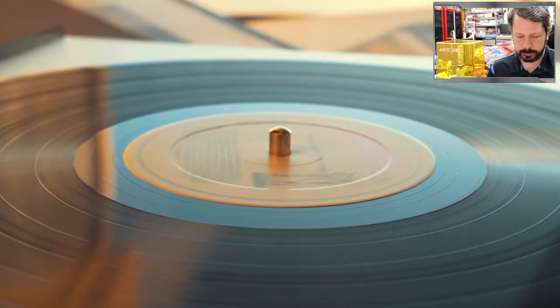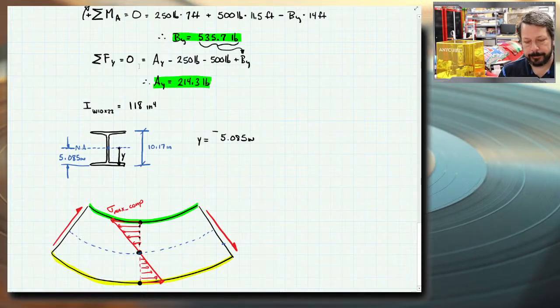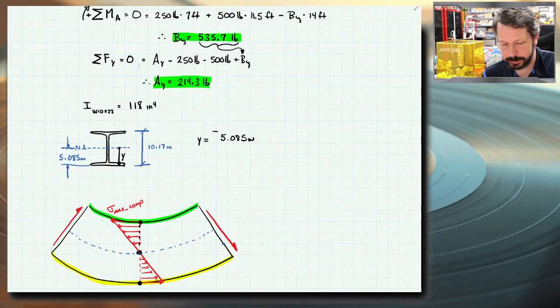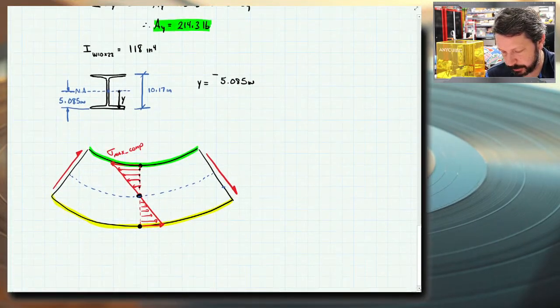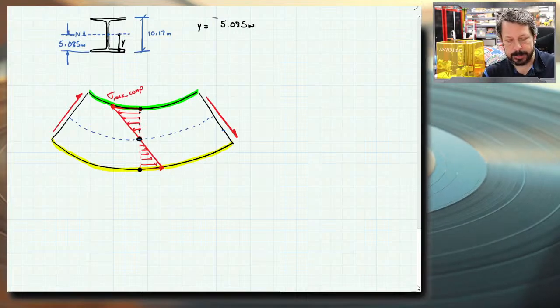Sheared, yeah, I did draw them the right way. It doesn't matter terribly much which direction, as far as the part failing. It doesn't matter which way you draw the shear, because it's going to shear one direction or the other with equal shear strength, I guess. But for later on, when we're deriving some other things with shear and bending diagrams, these arrows matter for their direction.